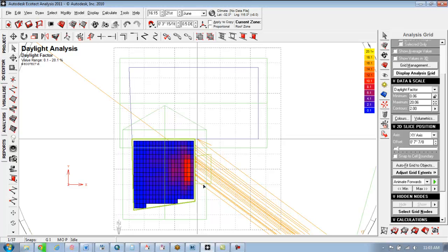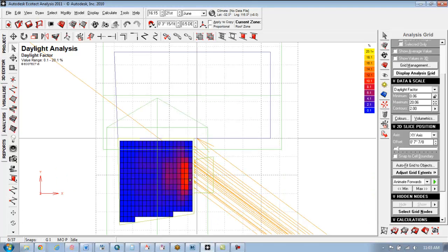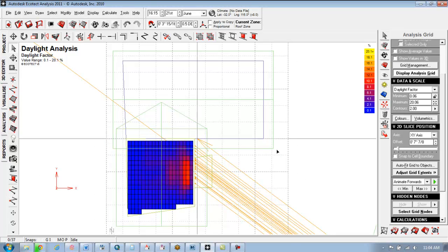And then, let's see how much you were paying attention in Steve's class. What's a good daylight factor percentage? What's that? Yeah. So like 4 or 5% is actually, you'd be able to see and read, you'd be okay. So with this one window with shading on the east side, for the most part, your room is going to be fairly dark, not surprisingly. But right under the window, the average daylight factor is going to be pretty good. You're going to be able to read just fine. So there you go.